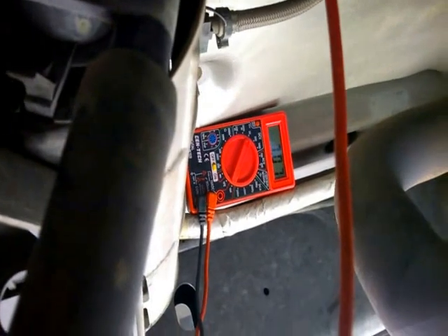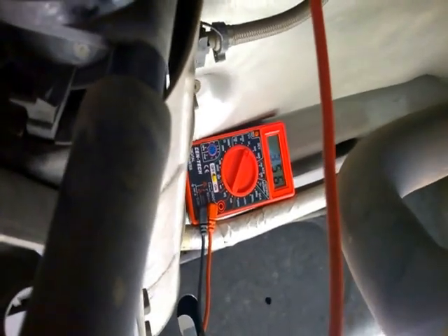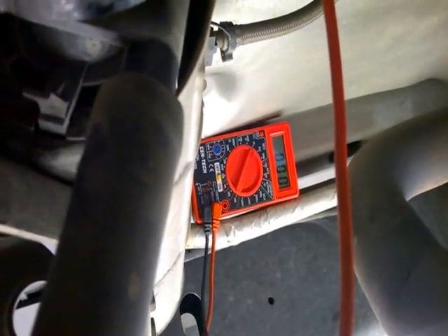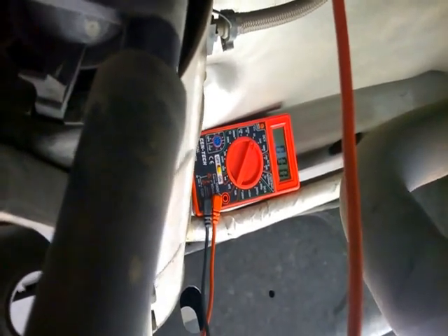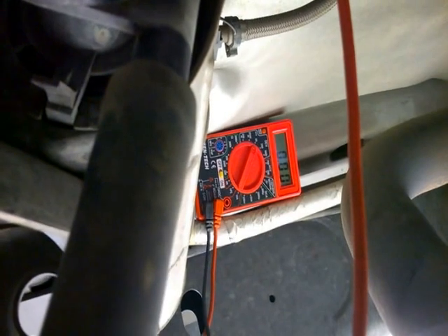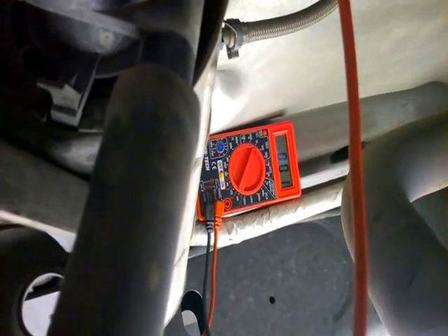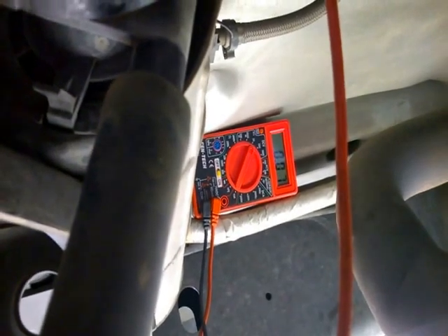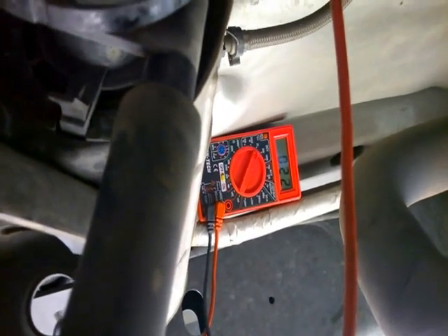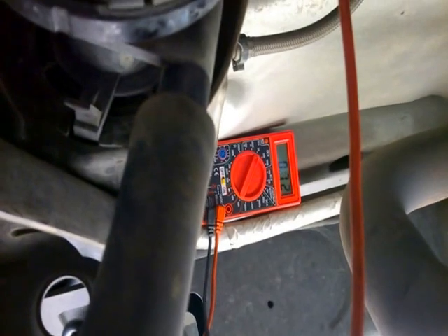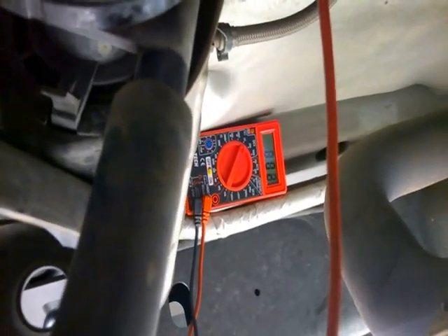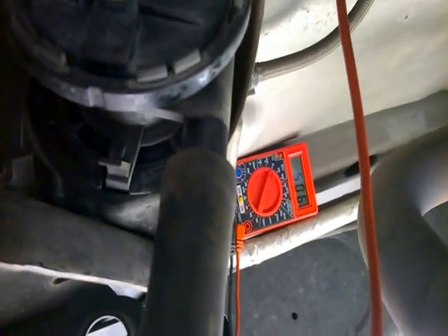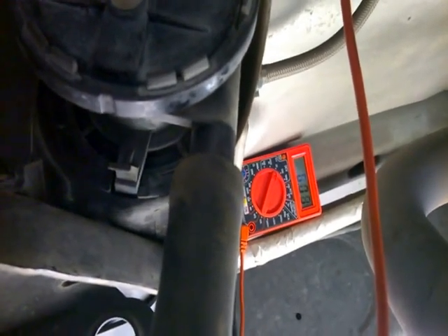And on the voltmeter, like I said, this is power side switch. It's also pulse width modulated, just like the Evap purge solenoid. The control command is fluctuating from 5 volts to 4 volts, 0 volts, 7. So that voltage is jumping around. So next, I'm gonna back probe the return signal, which is the ground signal.